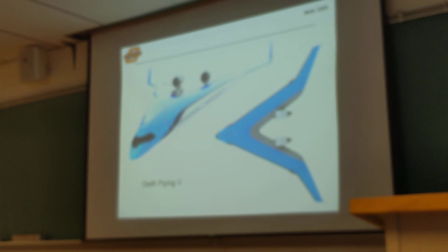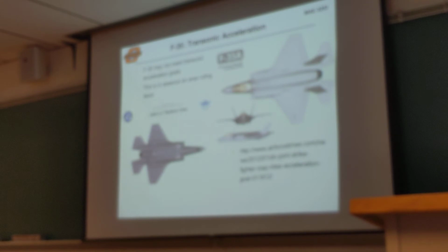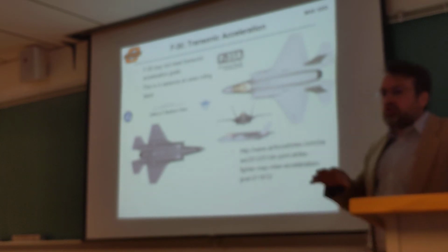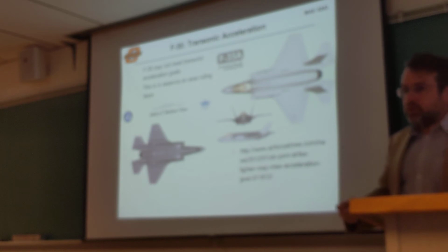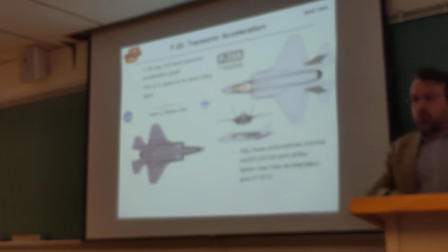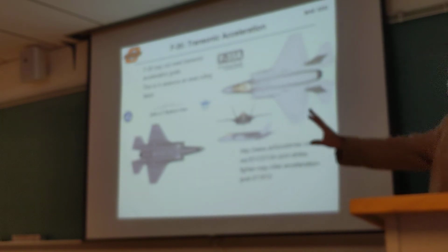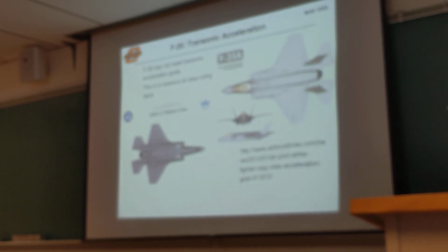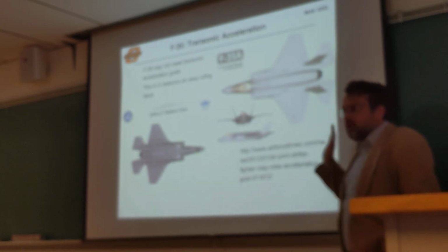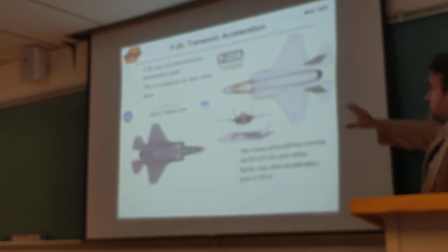Okay. Now, interestingly enough, this is actually a problem with the F-35, because when it was originally being test flown, it ran through issues related to transonic acceleration. Recall that the whole goal going from subsonic to supersonic is just to get through the transonic regime as fast as possible so that you don't have to worry about it. You don't want to spend any other time there, and it wasn't able to accelerate fast enough through that wall, which is essentially an area ruling problem.